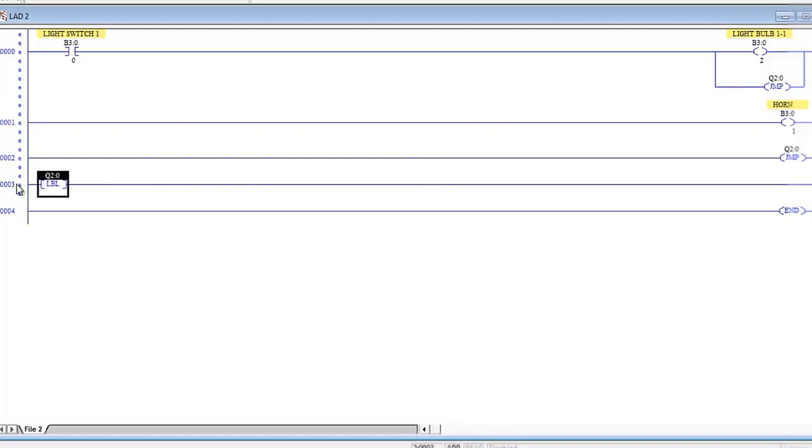Now, here's something strange about a label. If you have a label on rung 3 with whatever instructions here, you cannot execute this rung unless you jump to it. In other words, if you have a label on this line and there's no jumps anywhere on your program, it will never execute rung 3. It will go from 2 straight to 4. So in order to ever execute a rung that has a label, you must jump to it,